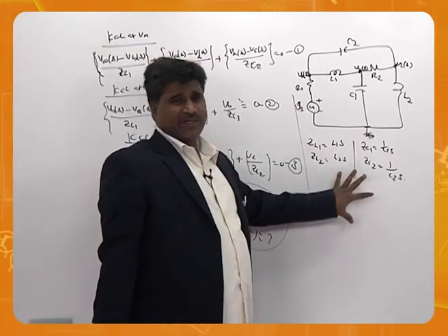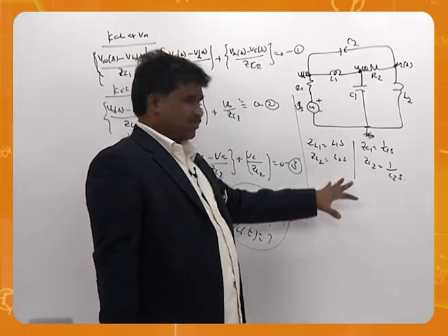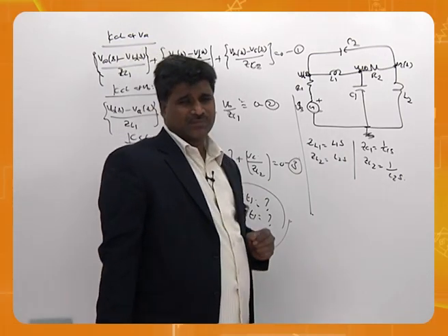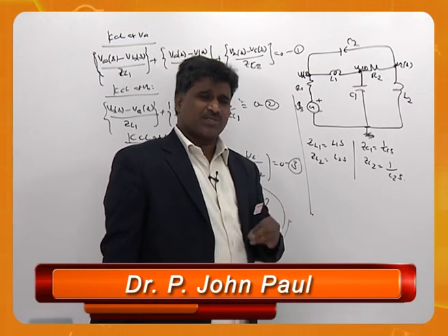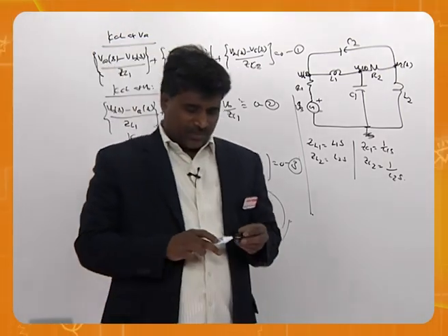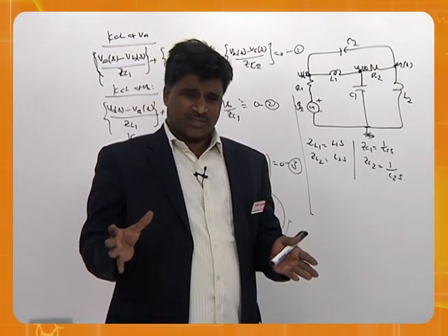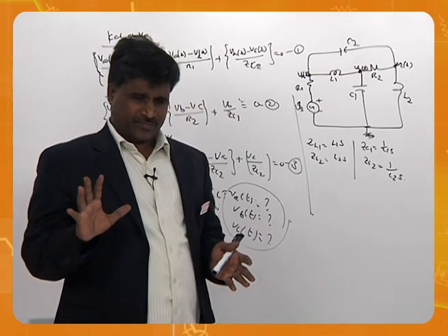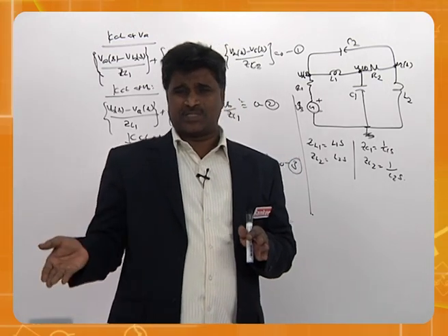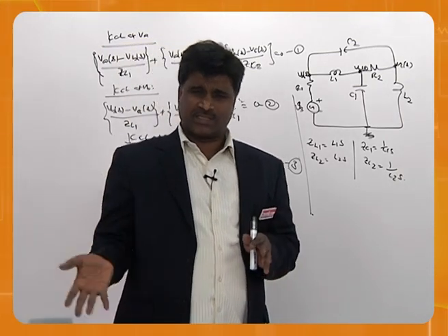So before going to S domain, convert them into S domain and use that as KCL. Once you convert them into impedances, you can treat them as resistors, just Ohm's law. So that is where S domain comes into the picture and helps us to solve. So that's the meaning of mesh and nodal. Therefore, my concluding remarks are very simple. As the circuit becomes complex, we have to go for mesh and nodal. From mesh we will calculate loop currents, and then branch currents and branch voltages. From nodal we will calculate nodal voltages. From there we talk about branch voltages and branch currents.